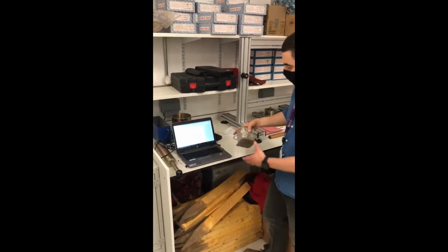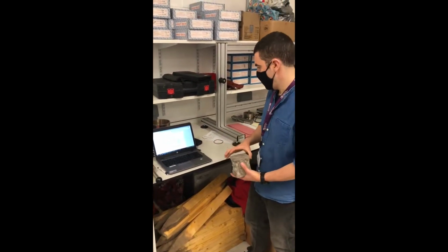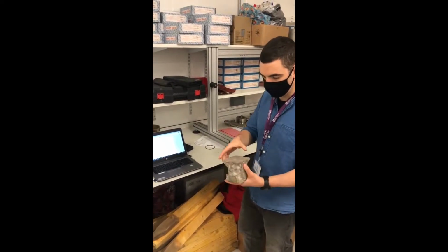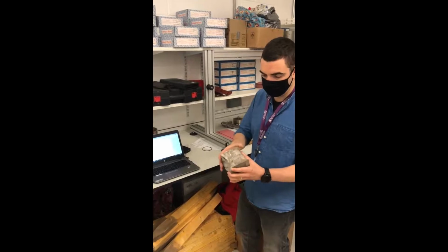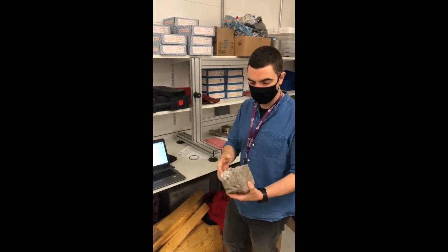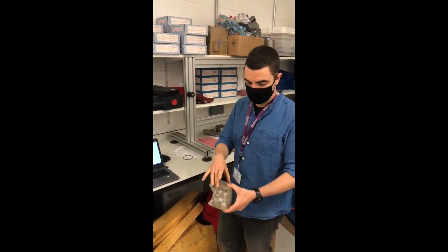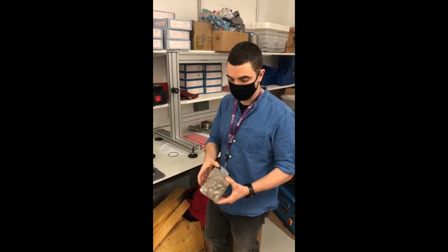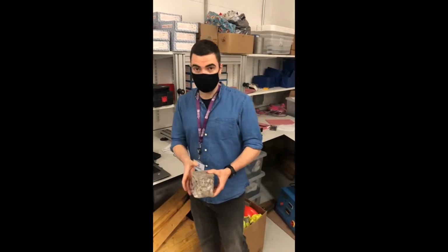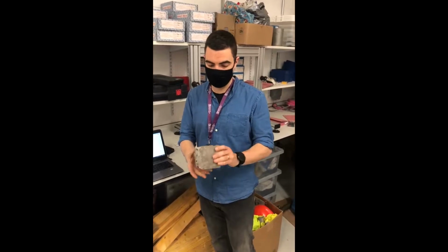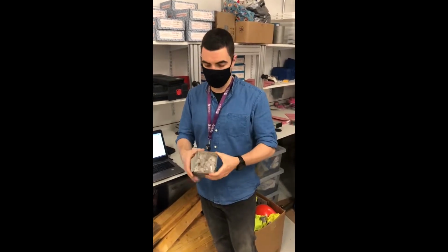It's obviously got quite a lot of it still intact, so it wouldn't be an explosive failure, and we could possibly still test this and see if there's any residual strength left. Obviously we'd need to calculate the area that we'd be testing, so that when we put our force through it, we'll see what compressive strength is left in that. So maybe do that just now.